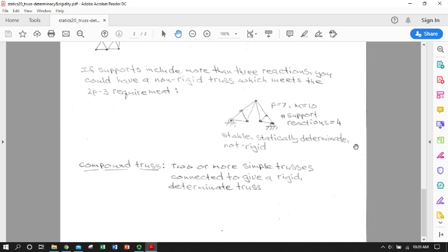So the last subtopic that we'll have with trusses will be the method of sections. And so that'll be really useful when you want to get the force in one member. Something to remember with method of sections is it will require a little bit more finesse. You'll have to make some judgment calls on where to put your section, but otherwise it's just more equations of equilibrium. And know that if you need to find the force in any member, in any truss, you can use either method. And as a suggestion, the method of joints, as cumbersome and long-winded as it is, tends to be simpler. It will always get you there.